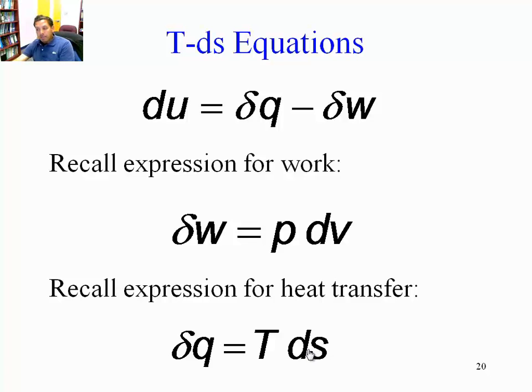Remember that delta S is equal to the integral of dQ over T. Likewise, we can say Q is equal to the integral of TdS. So essentially, the heat transfer is the area under the curve in the TS diagram, the same way we said that the work is the area under the curve on a PV diagram.